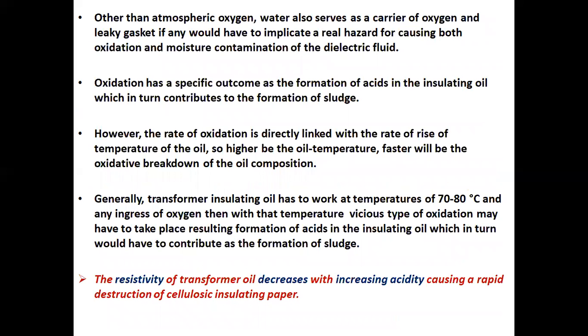Other than atmospheric oxygen, water also serves as a carrier of oxygen, and a leaky gasket, if any, would implicate a real hazard for causing both oxidation and moisture contamination of the dielectric fluid.